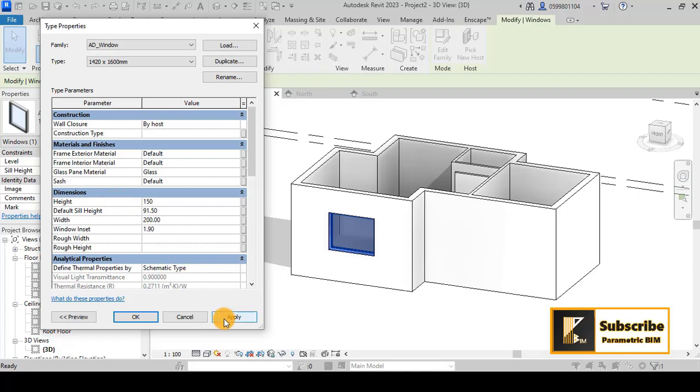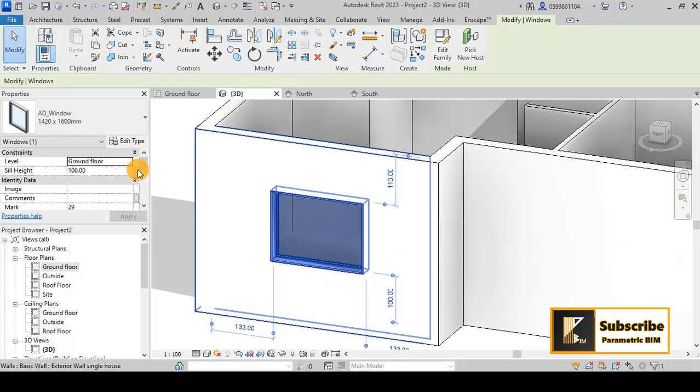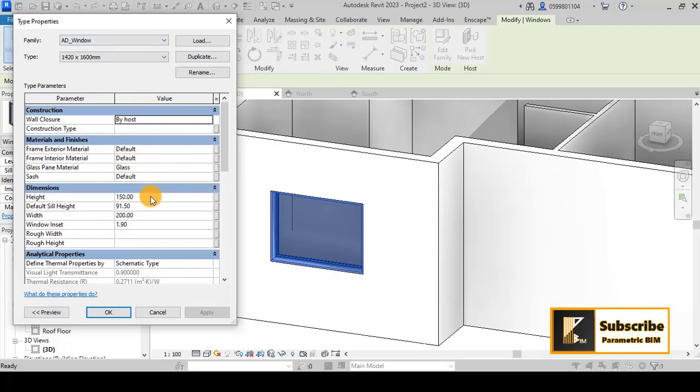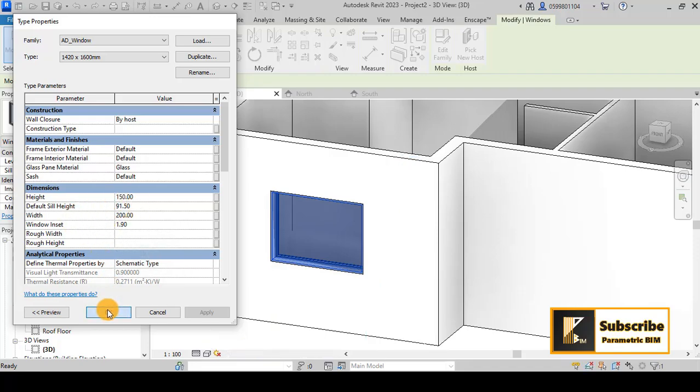So once I click apply, you can see that it will be changed. Maybe it is not obvious to you. Let's say 100 and apply. You can see that it will be changed automatically because we have these parameters of the dimension. So this is the way how you can change the height of the window, the cell of the window, the width of the window, and the parameters also that we have in this family of this window.